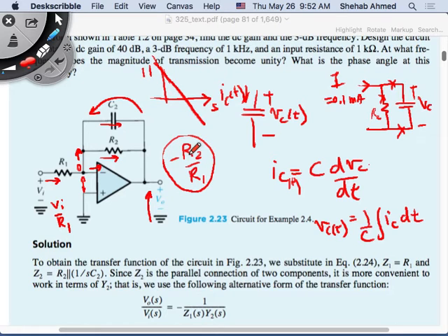So the effect of the resistance is adding infinite gain, and the fact that if I make R2 infinite makes the gain infinite. And the fact that the capacitor is open circuit at DC means that it has no effect on what's happening at DC if I remove this resistor. Right? What does this look like?